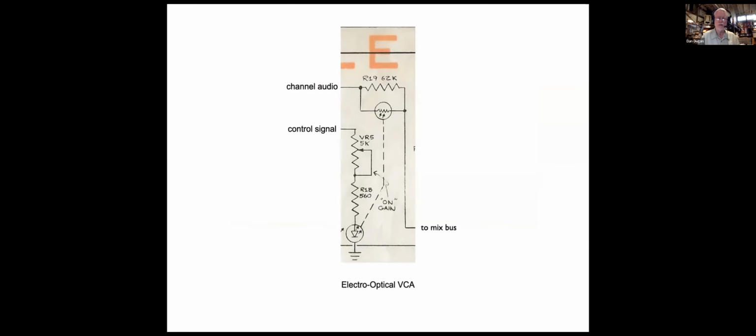And then you also need a VCA, and of course in 1968 and 1969 there wasn't much of a choice for VCAs. There was a device made by a company called Vactech, which was a cadmium sulfide cell and an LED. Of course, LEDs were brand new at that time. And they were packaged together so that when the LED lit up, it illuminated the cell, and the cell would drop the resistance of the photoresistor. And that was quite effective and very quiet, and led to optical compressors, which were very successful at the time, and emulated in digital circuitry now.